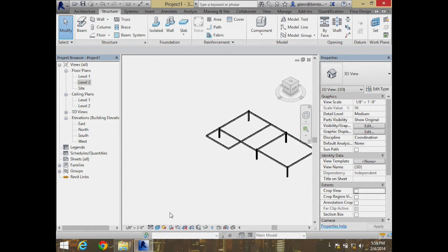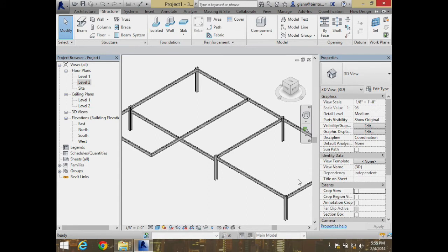What will happen on things like this often is, as we set up stuff like this, we now have these different systems of beams, and we can start thinking about how we want to start framing up the joists within here. What will happen is, under the steel deck, given this span, it's going to need a little intermediate support, because typically, for the steel deck between like 5 or 6 feet, you don't take it so far before you introduce some intermediate support.